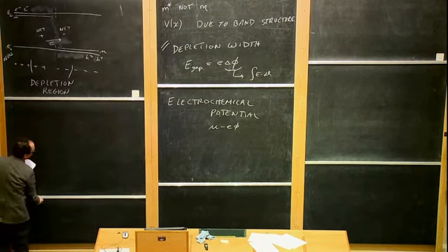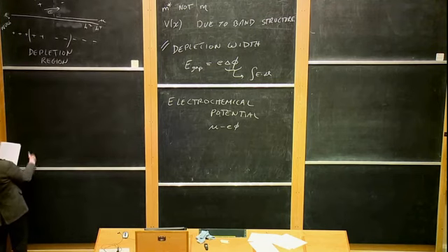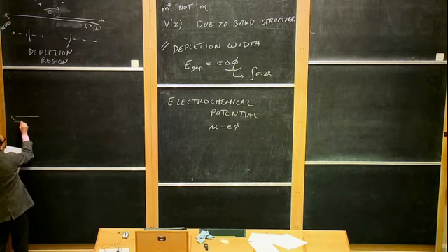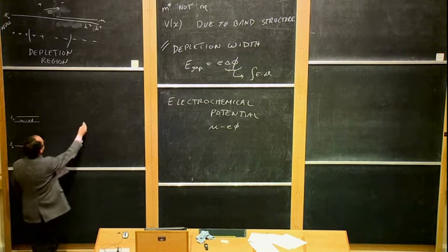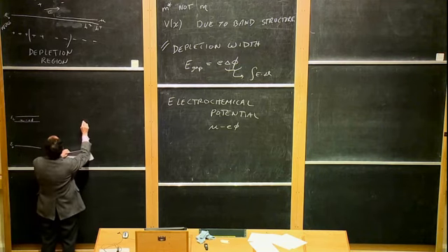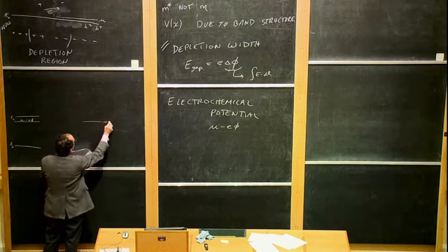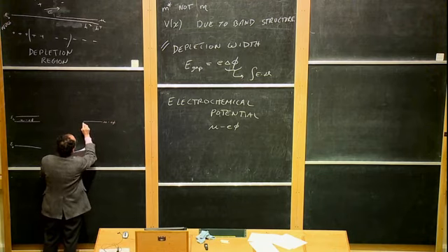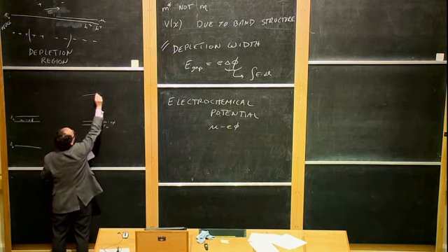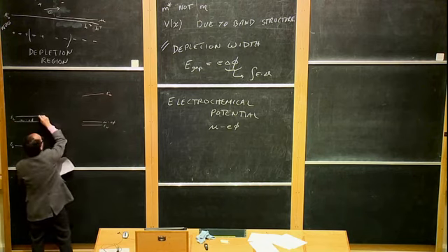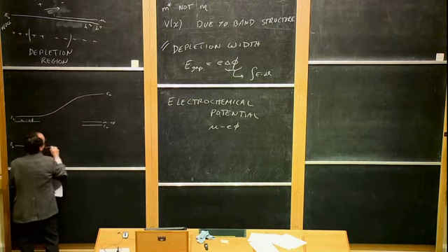So over on this side, we'll draw the same picture we had before. We have the conduction band energy up here. The electrochemical potential we'll put here, so this is mu minus E phi. We have the valence band energy over here, E valence. Now over here, on the other side, we line up the electrochemical potential exactly the same. But here, the valence band energy will be here, E valence, and the conduction band energy will be up here, E conduction, and these get connected together like this.